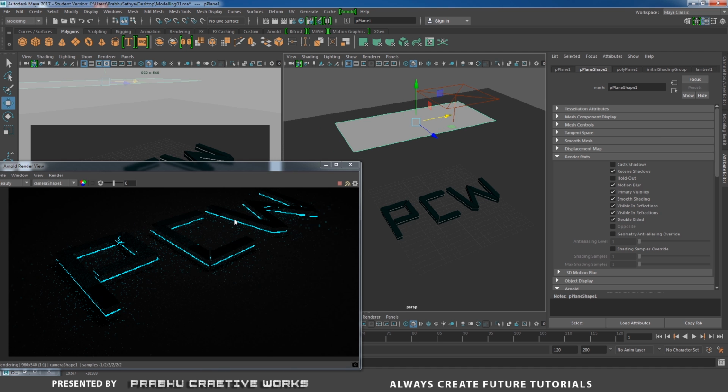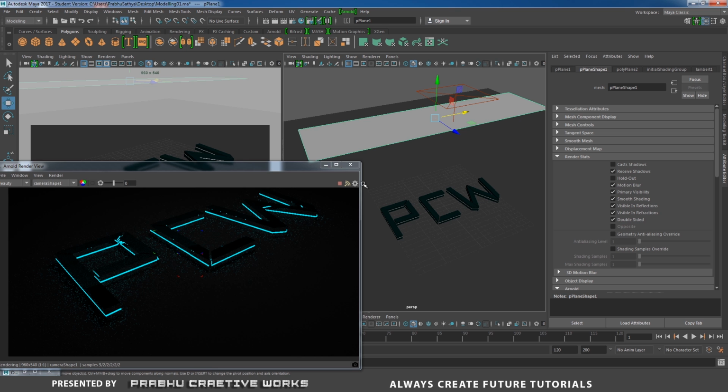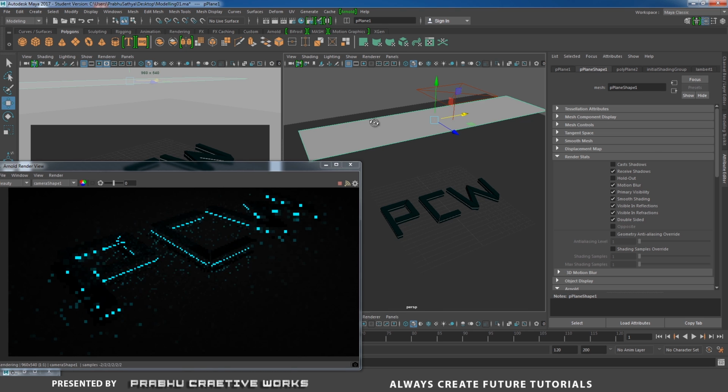like this. You want to cover the 3 text. Press R and scale in X. So you need to adjust until you get the perfect result. So I will move in X. Now you are able to see the reflection. If you want to see the reflection clearly, you need to apply a surface shader for this card.